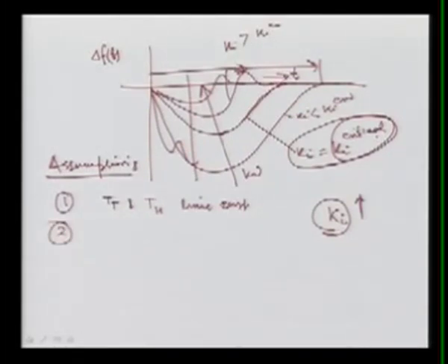The second assumption that we made is that the speed changer response was assumed instantaneous. It was thought that the speed changer, that is your governing system, acts instantaneously. Whenever it is required, it is suddenly given, but this is not always true. Third, we assumed no non-linearity in the equipment, such as deadband. You can see here we are having some deadband in which your machine operates. So we have neglected all deadbands and non-linearity in the equipment in this analysis.